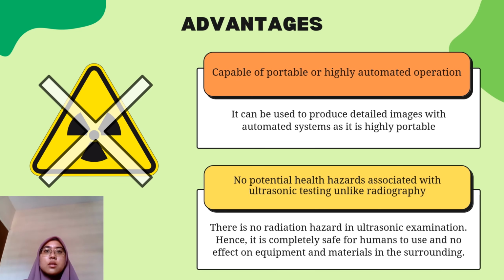The third one, ultrasonic testing is capable of portable or highly automated operation, where it can be used to produce detailed images with an automated system, as it is highly portable. Next, ultrasonic testing does not have potential health hazards, unlike radiography. There is no radiation hazard in ultrasonic examination, hence it is completely safe for humans to use and has no effect on equipment and materials in the surroundings.